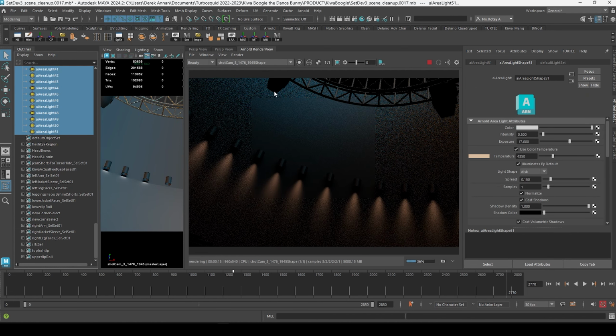All right, so I'm going to start by creating a polygon cylinder. Move it up. Scale it up. Down. And I'm going to select these faces and go select inverse and delete the insides. I'm going to get this edge and scale it down to get that shape that I saw in the Amazon camera. And I'm going to extrude, push inward, to make it shorter.